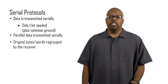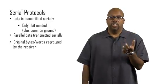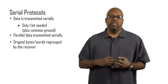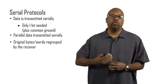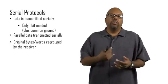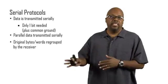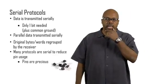The reason why we do this is because it saves us pins. What has to happen is these 8 parallel bits are sent one at a time, and at the receiving end, they have to be received one at a time, but grouped back into 8 bits. We need the original 8 bits back. So they're received one at a time, and once it gets 8, it says, okay, this is a group of 8, that's a byte, and it sends it off and processes it. So we do this to save pins.